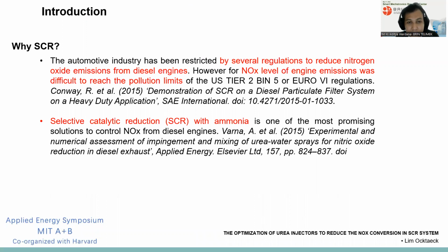Why the SCR systems? As you know, the automotive industry has been restricted by several regulations to reduce nitrogen oxide emissions from diesel engines and heavy-duty diesel engines. And selective catalytic reduction with ammonia is the most promising solution to control NOx from diesel engines and heavy-duty diesel engines.